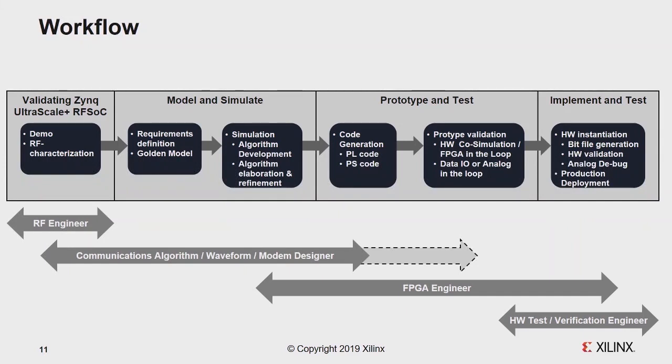And there's really two types of code generation. There's the hardware code that goes on the PL, the programmable logic, and then there can be firmware or software that goes on the A53. And they can be interrelated. So how do you generate that code? Okay, so we'll call that the PS code.